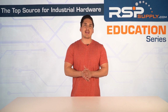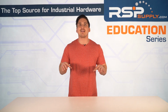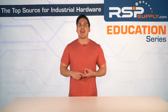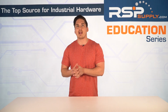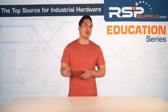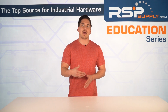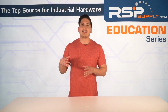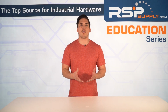All right, let's do a quick recap. We explored the fundamentals of how industrial devices communicate, the invisible threads that keep automated systems running smoothly. We broke down serial versus parallel communication and learned why serial is the go-to industrial protocol for long distance and reliable data. Then we tackled synchronous versus asynchronous communication and how the presence or absence of a clock signal is going to impact speed, timing, and reliability in your systems. Finally, we compared analog versus digital signals, showing how each has its strength depending on the application. Precision measurements for analog and fast, noise-resistant control for digital.